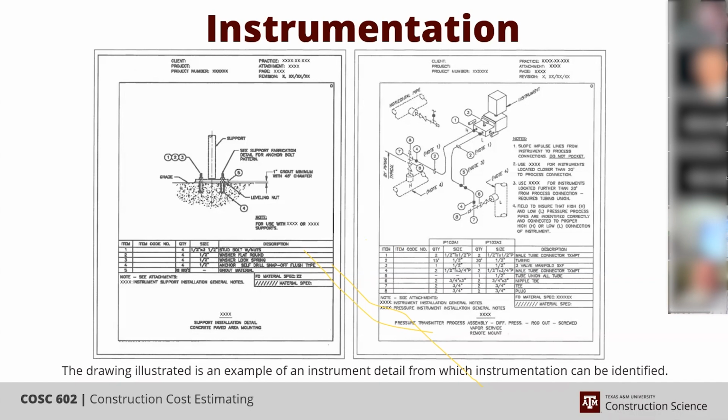That one on the right is an impulse one. You see how it has those little valves right there in between, like the 1 and 3, has one on the side, one on the top, and one on the other side. The flow comes through there. You can block those two, close those two on the sides, and open that one in the middle, and then back flush that transmitter, and then you can line it back up the right way and get your reading back.